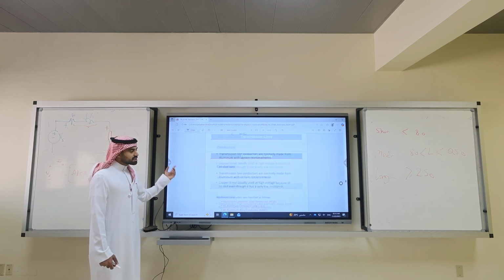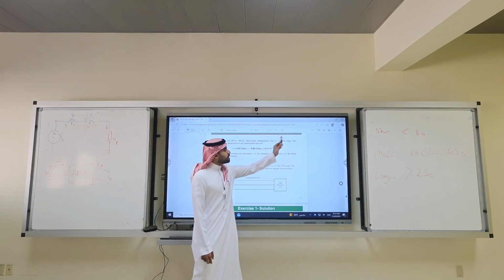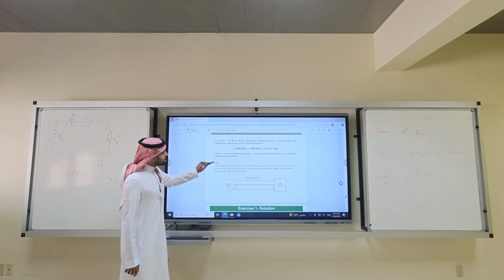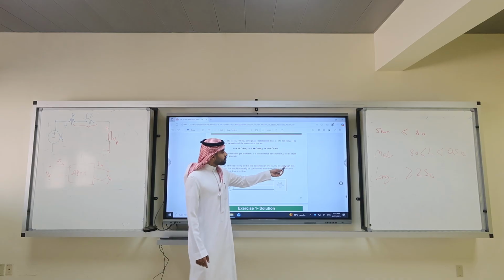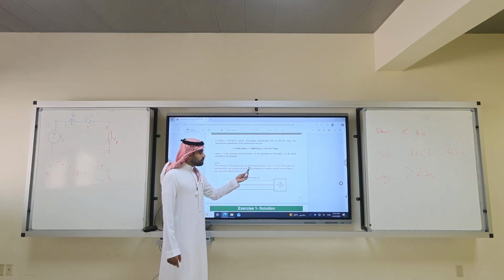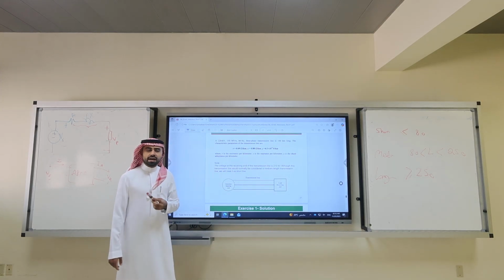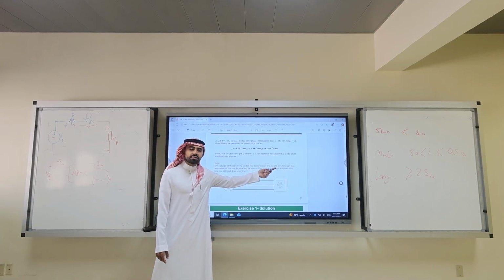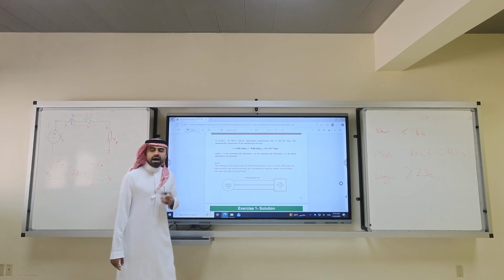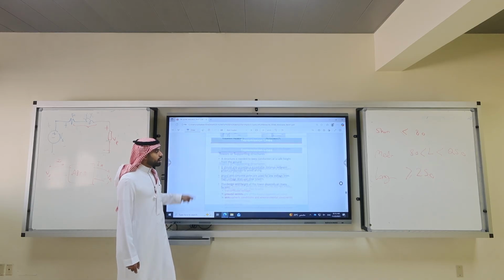In the last exercise, which is made for practice, he's telling you a transmission line of 140 kilometers, but he's writing a note. The voltage at the receiving end of the transmission line is 210 kilovolt. Although this line is medium, they will treat it here as short to simplify analysis, and at this voltage level, maybe the differences are not that much. The higher the voltage, the higher the capacitance. Why? I will show you later why.